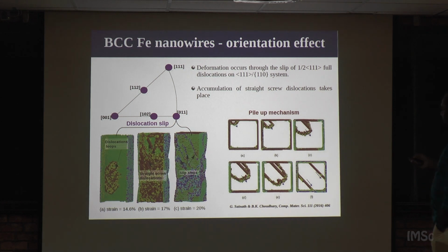Now, after that, how do the dislocations multiply? As we have said, in bulk crystals dislocations multiply by the well known Frank-Read mechanism, but due to the very small size that mechanism no longer operates at this size scale. So, let us see here: the dislocation first nucleates from the corner, then with increasing strain it grows. It is basically a mixed dislocation. It means the Burgers vector is the same but the character of the dislocation at some points is edge, at some points it is screw. So, with increasing strain the edge part will move faster than the screw. These are the screw parts, this is the edge part. The edge part will move faster than the screw, so what is left is only two screw dislocations. So, basically one dislocation has become two dislocations. This is some kind of multiplication mechanism that we can see in nanowires.